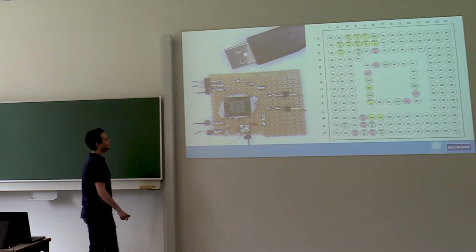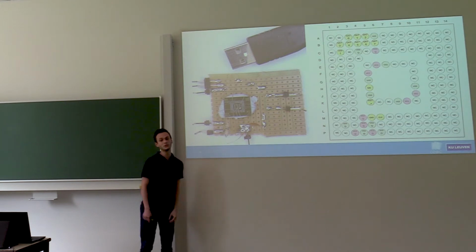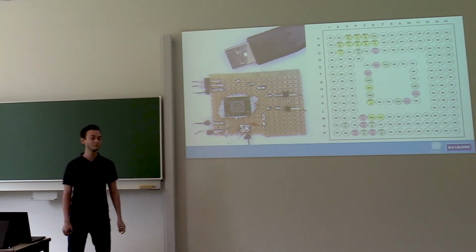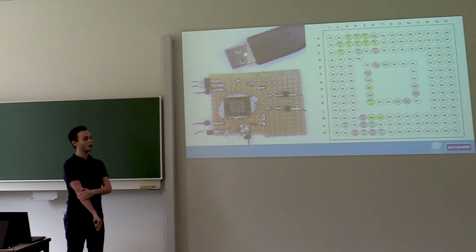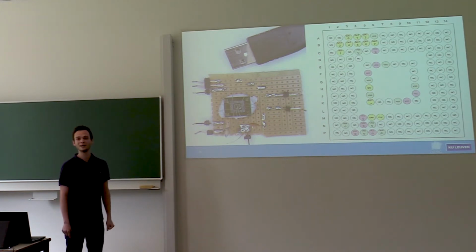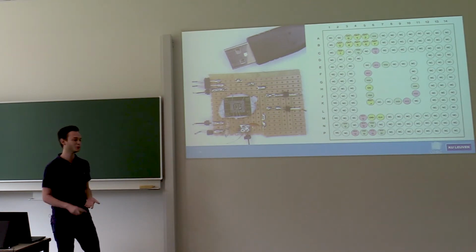This is the eMMC chip from the vacuum cleaning robot. So that one we took off using hot air. And then you have basically two options once you have the chip off. You can buy an expensive reader or a BGA socket to put it in.